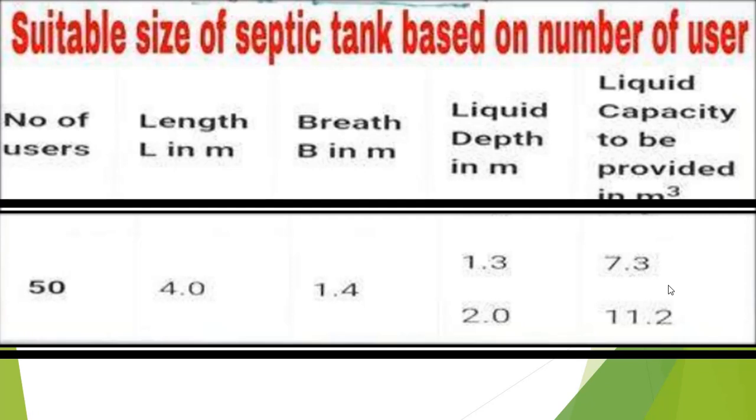Now here I have listed the point-wise requirements of design of a proper septic tank. So listen carefully. First, the capacity of the septic tank should be sufficient to hold liquid, taken as 130 liters to 170 liters per member. Second, for the best design of a septic tank, the mortar used at the wall of the septic tank should be of thickness more than 20 cm, and concrete used below the septic tank should be of M15 or M20 grade.